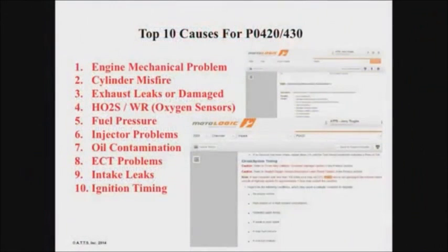Oxygen sensors and air-fuel ratio sensors. Are you checking them right? Did you get the right part? Are they working right? Are they lazy? I mean, I've come across a lot of different nightmares where people try to cut wires, put them together, put the wrong sensor in the car. Sensors have those little fins or slits on them. Why does the original one have 8 holes in it or 4 slits, and the one you're putting in has 3 slits or 2 holes? It does make a difference, gentlemen.